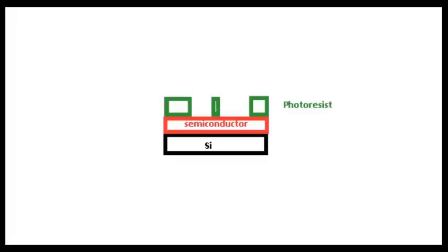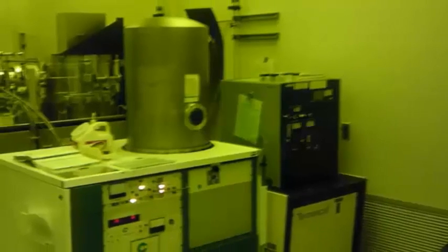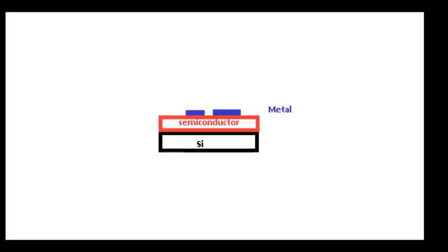The photoresist becomes sensitive to development after exposure, and gets removed only where it is exposed using a solvent. After the patterns are developed onto the photoresist, the metal is deposited on top, by either thermal evaporation or sputtering. Then the remaining photoresist is removed, along with the metal that was deposited on top of the photoresist, leaving metal in the same patterns as defined on the mask.